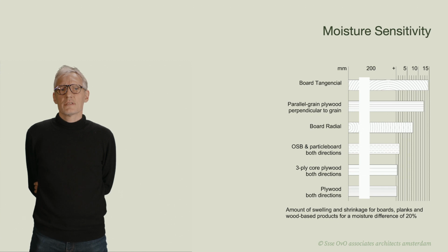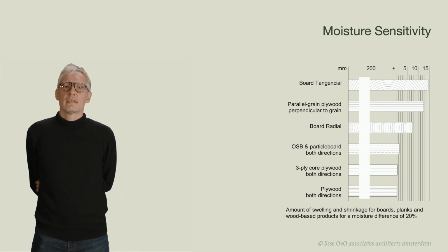While wood-to-wood joints have their strengths, they also come with inherent limitations that architects and engineers must consider. One of the most prominent issues is moisture sensitivity. Wood is hygroscopic. It expands and contracts with changes in moisture content. This behavior can compromise the fit and long-term stability of the joint. Specialized coatings or moisture barriers are often needed, especially in environments with significant humidity fluctuations.